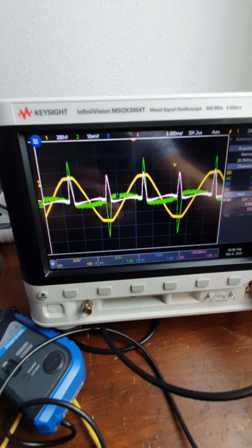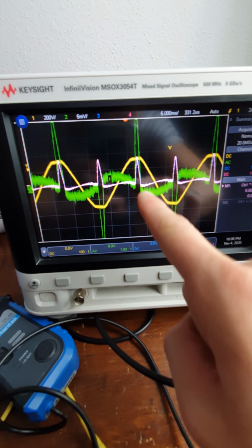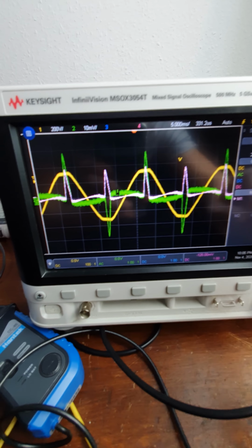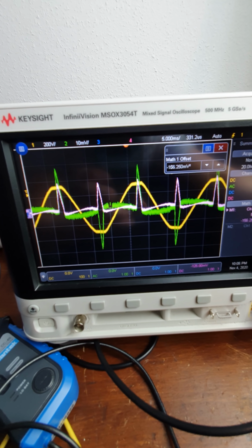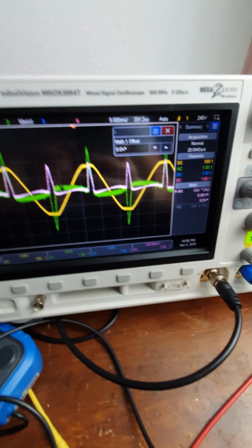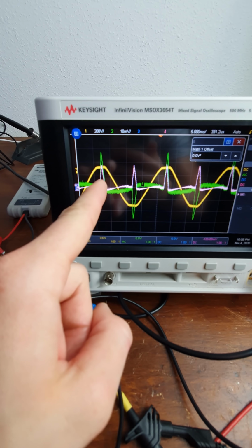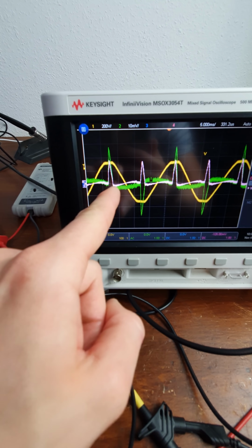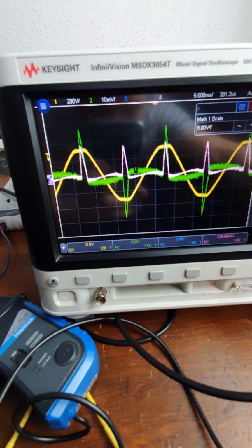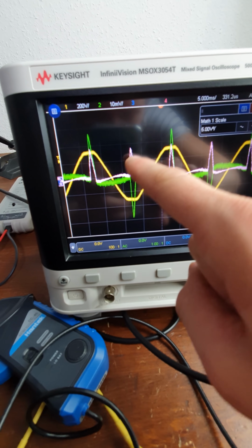And as you can see, we got the current flow, which here is a big spike and then it goes a bit negative, a bit positive. And basically what we have with the pink one, which I'm playing around with right now, is the power, the real power. That's the multiplication of the voltage and the current at every point. As you can see, it's a lot positive there.